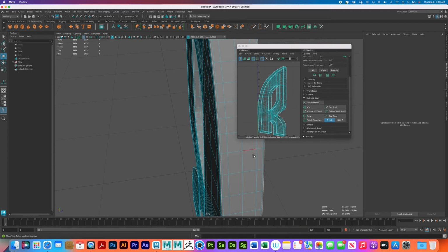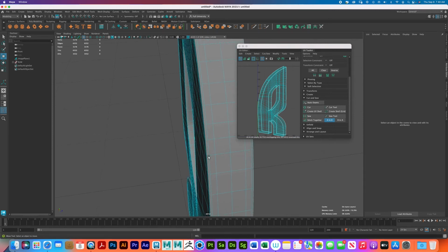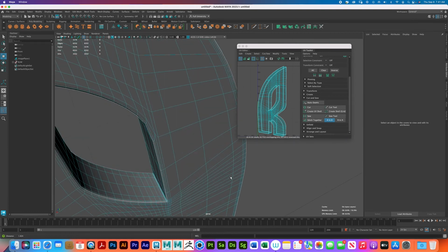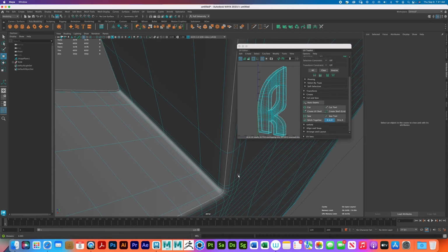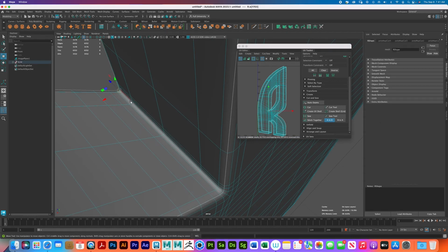I have front, back, I have this whole surrounding and the inside surrounding. But when you're working with this, you're gonna have to pick, unfortunately, where you want your seams to be. Most of the times, I usually pick a place like this. So click, shift, double click to where I want it to end, and cut that.